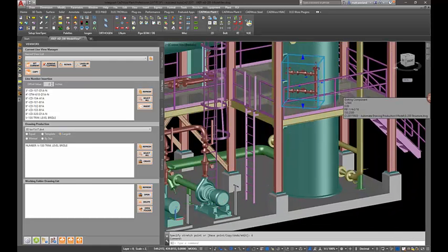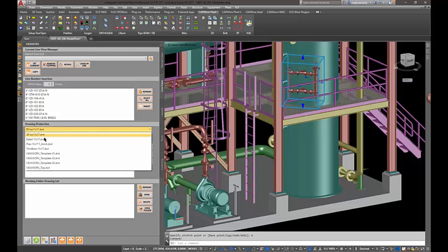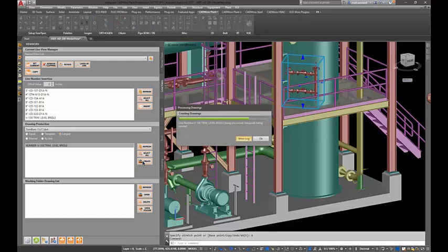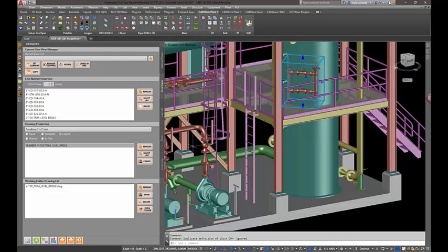So we have that finished, and to create the drawing, we again just look through our list of templates that we've created. This time I'm going to do the trim BOM, and we can set our scales either equal to the manual settings, by size, template, or largest. Since we already have our template created with the correct scale sizes, we could go that route. But since this is a detail, your template's typically not going to know exactly what size of detail you're working with, so I'm just going to tell it to choose the largest that it can find for each viewport. I select that and hit create, and now we have a drawing down below.